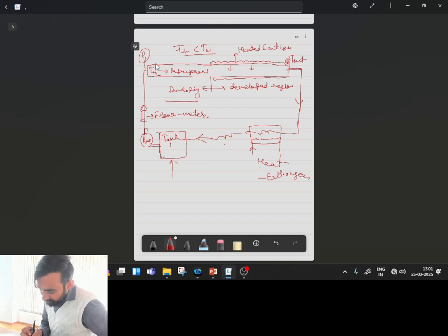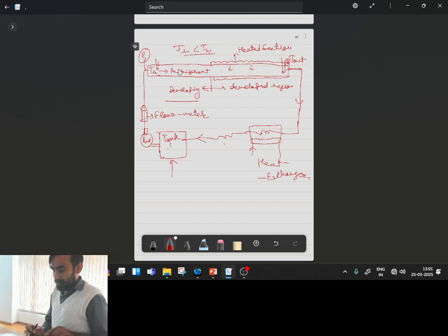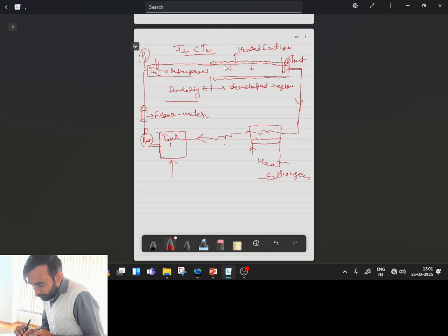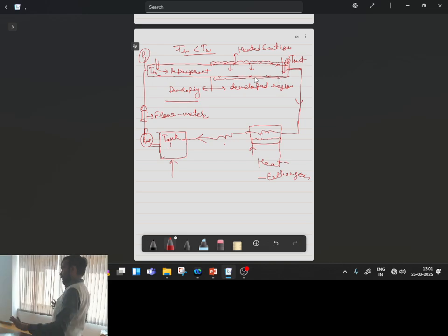What else do I need to measure? I need to measure the temperature. So for measuring temperature, I need to insert a thermocouple within the tube first to measure the temperature of the refrigerant, and other than that, at the wall of the tube to measure the temperature of the tube wall. Is this one clear? Other than that, here also I need to put thermocouples at multiple locations.